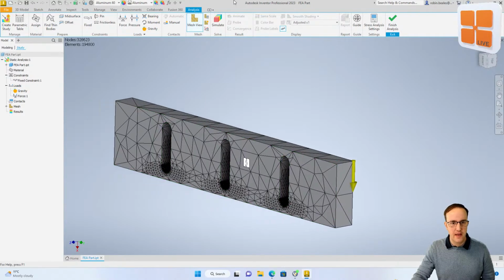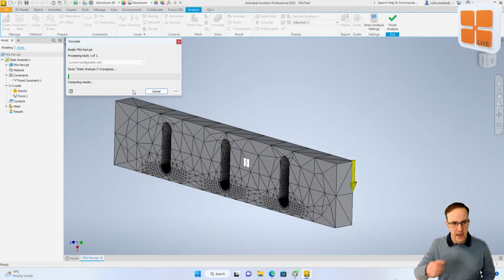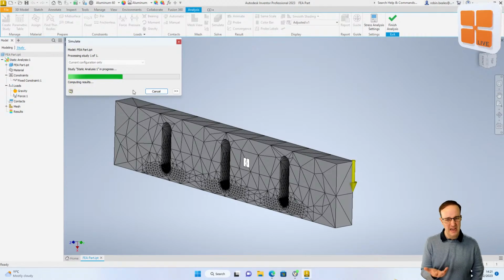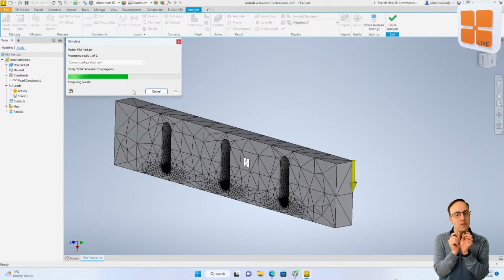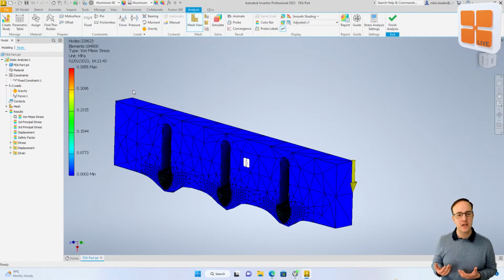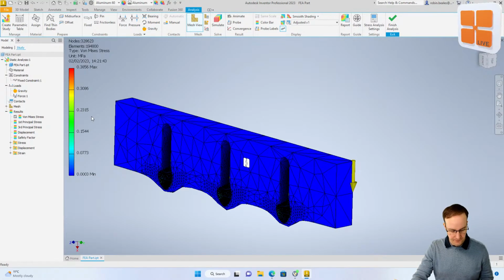But with those loads on there, we can go ahead and press simulate, go ahead and press run. It should still be fairly quick. It's not really doing anything complicated from this perspective, but it's doing it on a much finer mesh on those spherical faces. So you're going to get more results, especially as those results are where I actually put the load. So we'll give it a couple of seconds, let it compute and show you what it's doing. What we're going to do after that is maybe we'll do a quick modal analysis to show you vibration because it is very fast, and then we'll drop out and do a quick assembly, maybe showing you something more realistic.